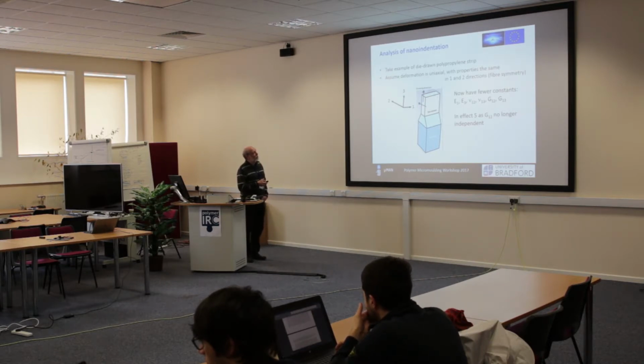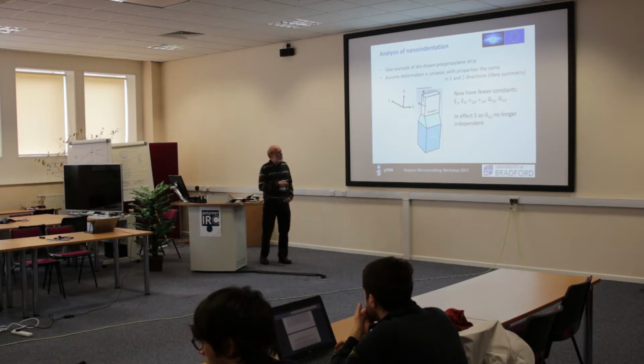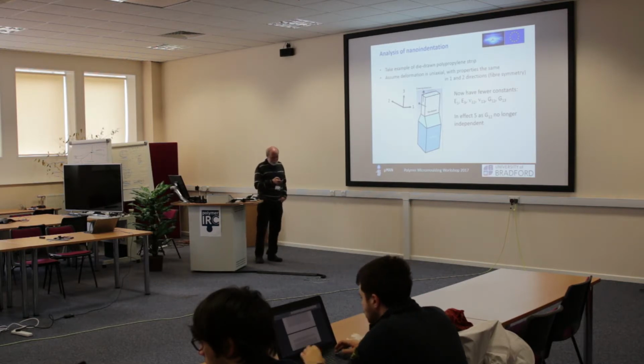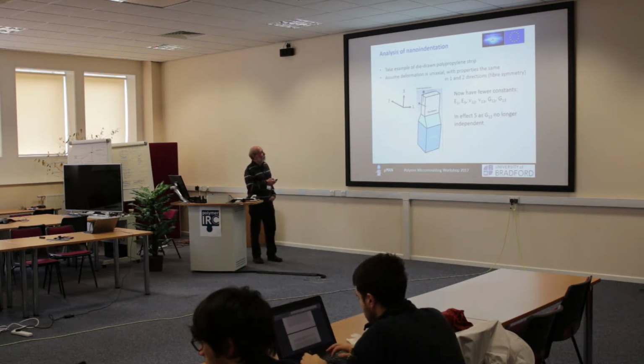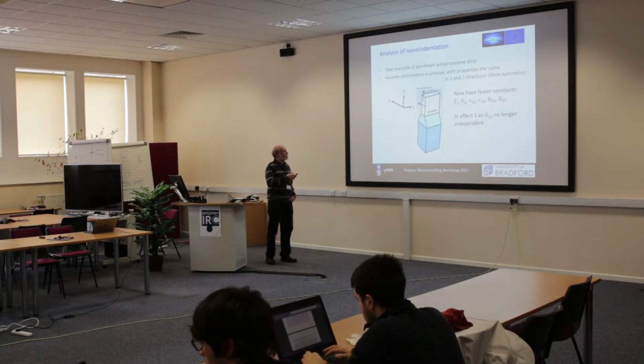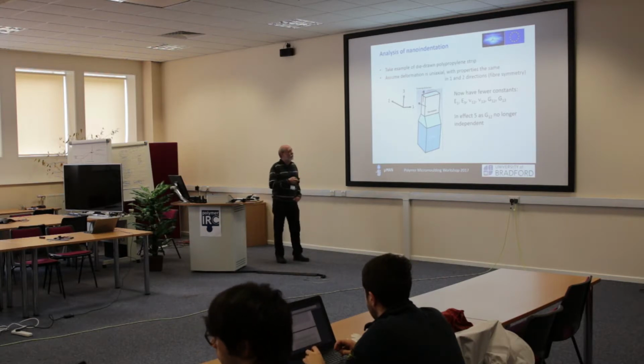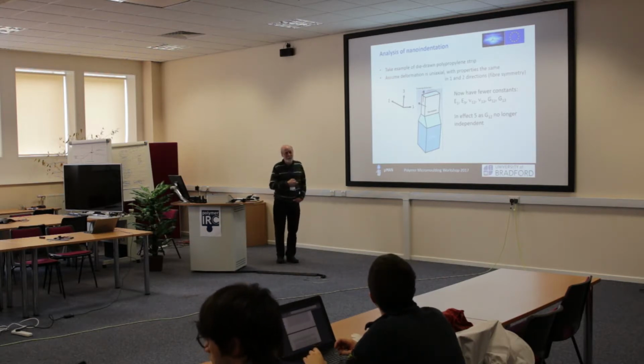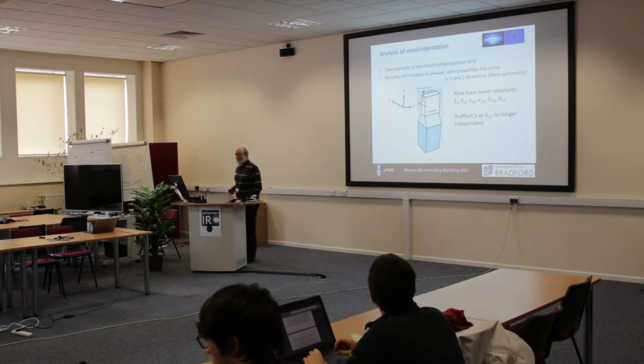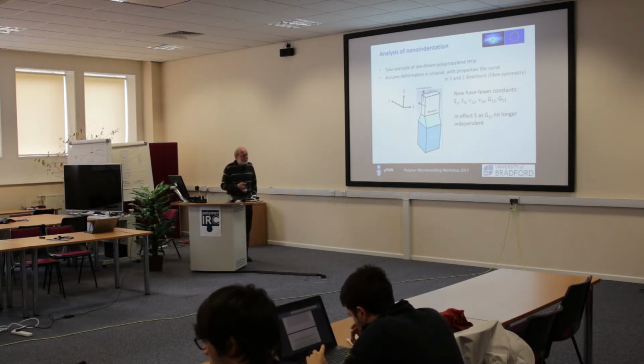This is an example because we have done nanoindentation experiments on it. We've done nanoindentation in two senses. We've done it indenting along the draw direction, so you're taking a relatively thick sample, so you can actually push the indenter into it along the axis, and also transversely. And we get different answers by doing that testing in different directions.